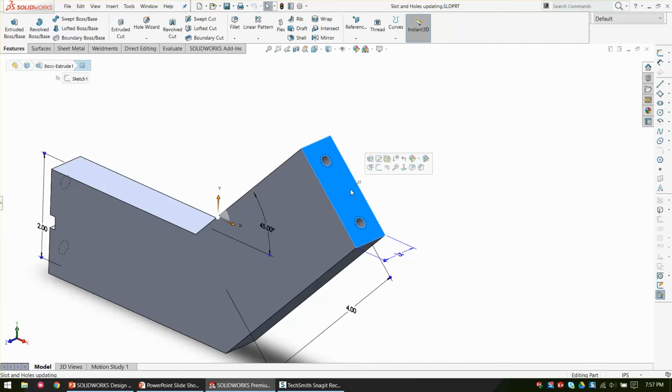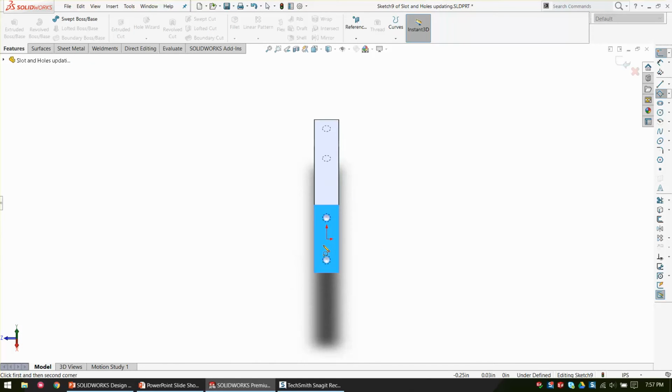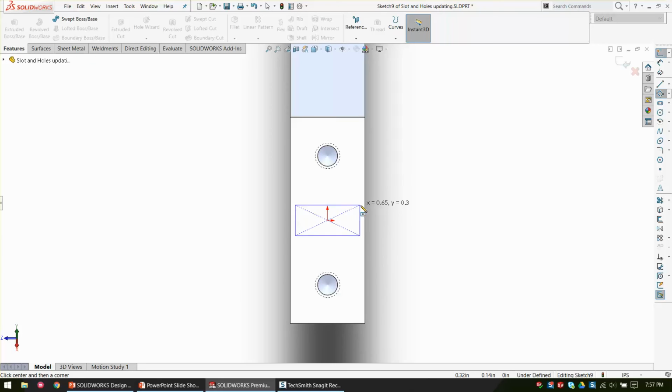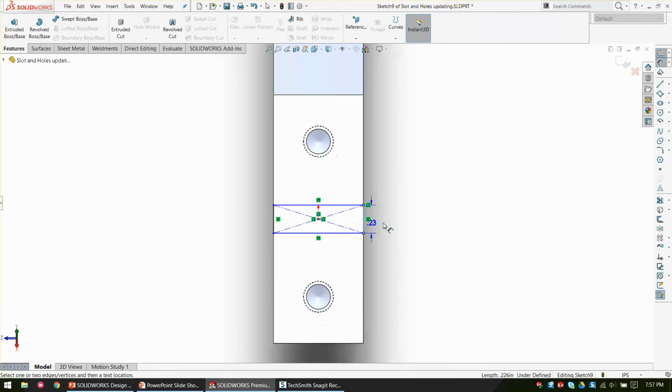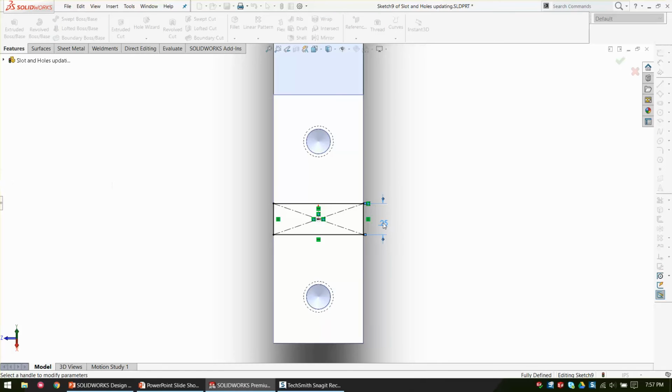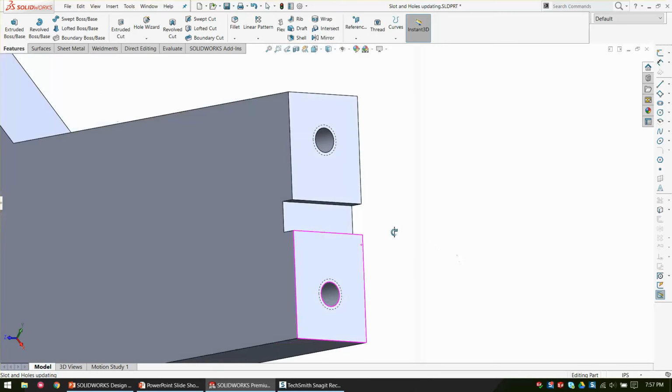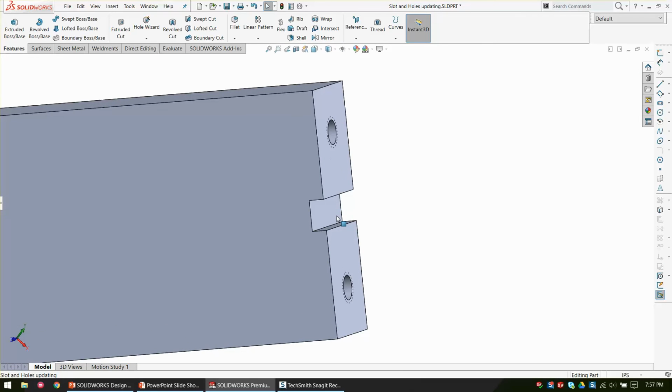Now most people would say, well, we need to cut into it, so I'm going to start a sketch on this side, draw my, and here we can do a center point rectangle because good design intent, we got our center origin, call this in 1/4 of an inch and cut down an 1/8 of an inch. Can't see my dialog boxes because they're hidden, but, right? That works for everybody, right?